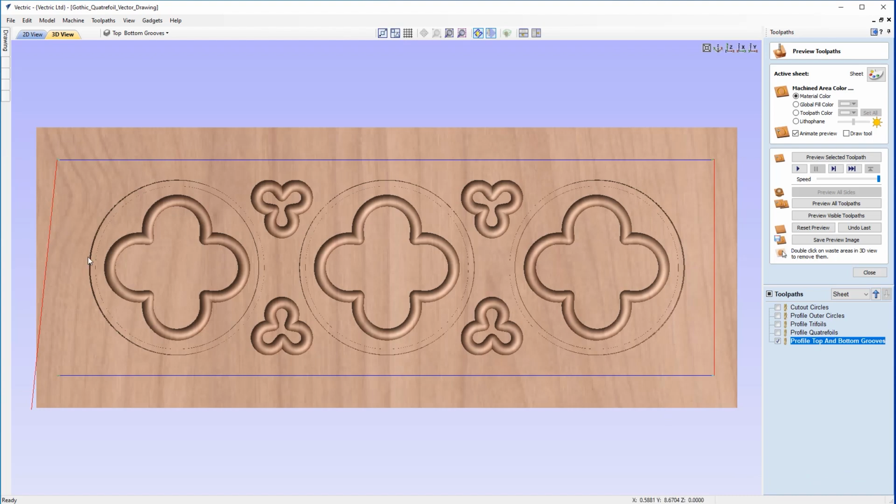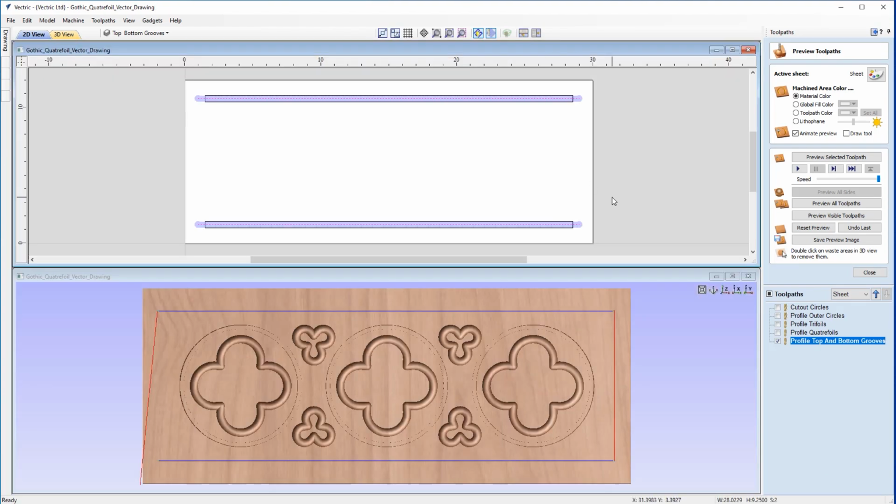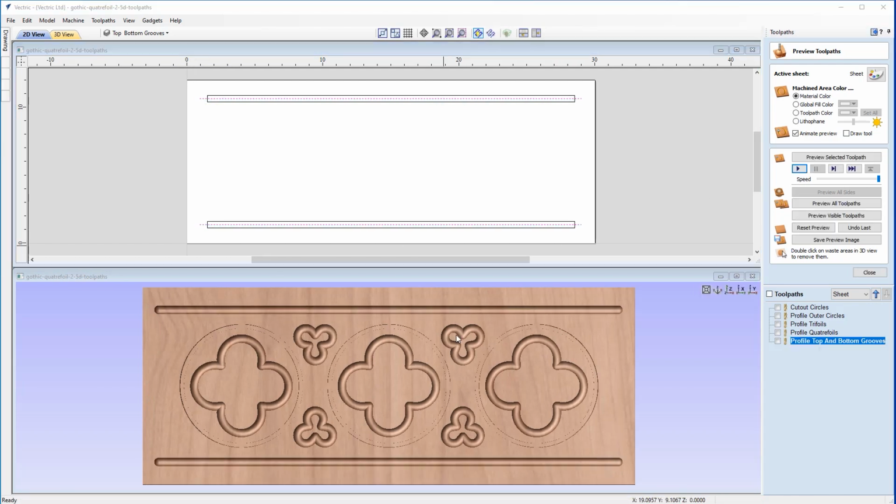And you'll see that toolpath shown there in the 3D view. We'll just horizontally tile that. And we can see up here in the solid view that the toolpath is extending past the ends of these vectors here. And then we can just play this. Now we can see these scallop lines on the top and bottom, which are now long enough for us to trim off to create that sharp edge. So that looks perfect, and now we can move on to adding some V-carving to our quatrefoil.